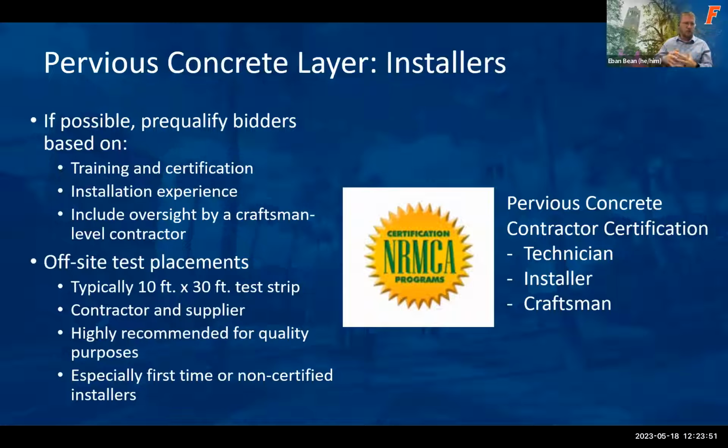As with any type of permeable pavement, highly recommend getting experienced certified installers. You can pre-qualify bidders by requiring they have certain training or certifications for doing installations. One of the other recommendations, if you're pouring stuff in place, whether it's concrete or asphalt, is to request a test installation or a test section be poured on site. That can help to identify any issues with the full installation. This is a really great step to include in the installation process.